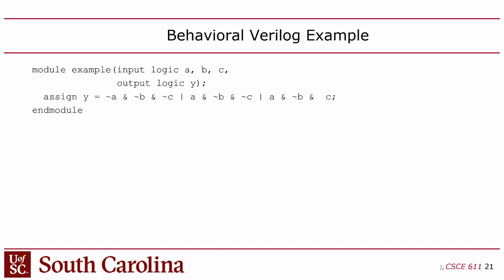So you've got a circuit that's driving Y, and so you don't want to drive Y with anything else, because this one statement has control at Y. Okay, so if you assign Y in another line of code, you're going to get contention, potentially. So this guy owns Y. He's providing the voltage on Y, and that is a sort of a concurrent blob of logic that will get synthesized. That statement will get converted into gates somehow by the synthesizer, the compiler.